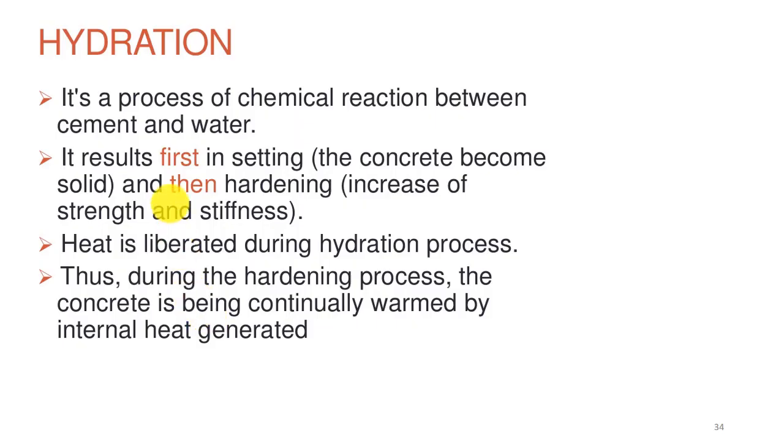Hydration reaction, I have explained it earlier. It is the reaction between the water and the cement products, in which different products are formed, like calcium silicate hydrates, ettringite, and thirdly, calcium hydroxide, which is undesirable for durability. If you discuss the hydration, you first have to define when your cement is going to be set, when is your initial setting and the final setting of a cement.